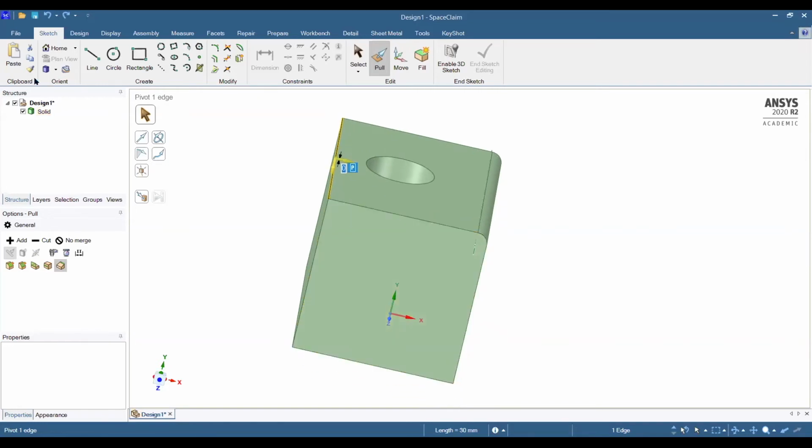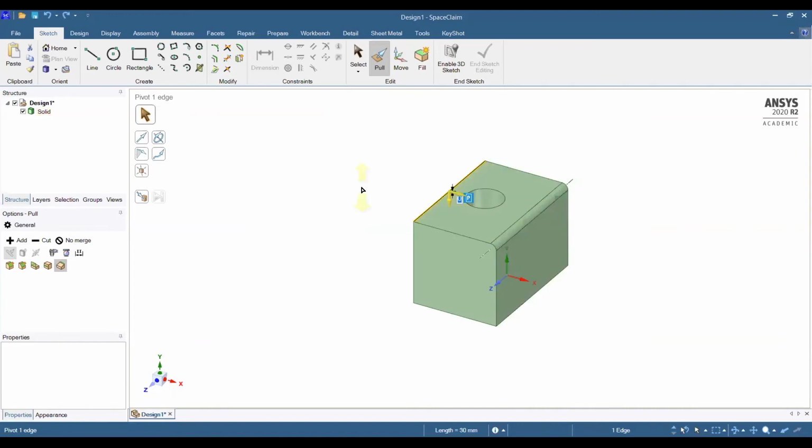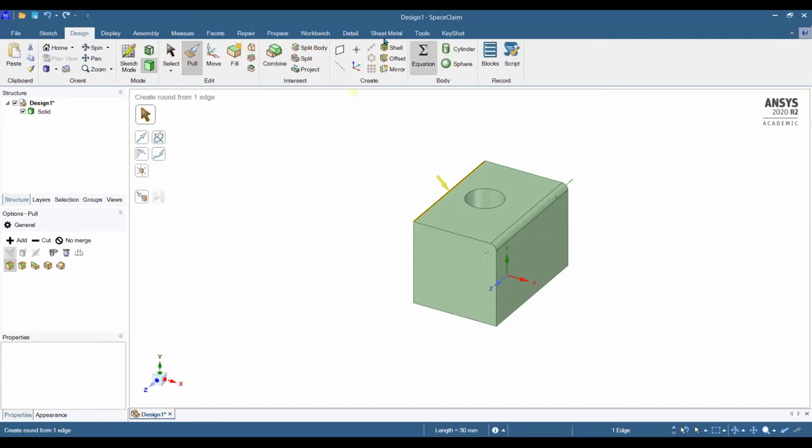All right, now say you have your object right here, and say you want to move it from point A to point B, not from 0, 0, but somewhere else. What I'll have to do is enable 3D Sketch and then end the sketch mode, but for you, the feature should already be here. So what you do is you go to your structure tree. If you want to move your solid or a component, press solid to have it highlighted and press the move feature.